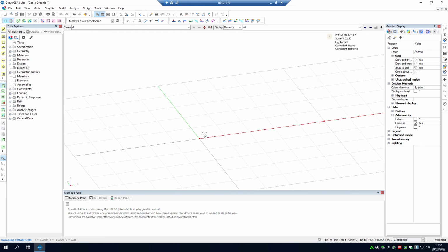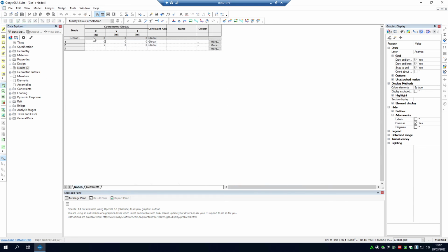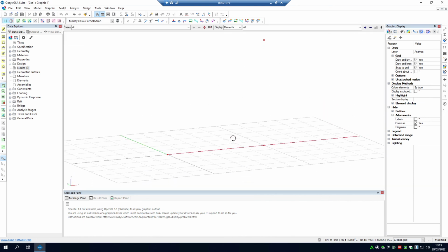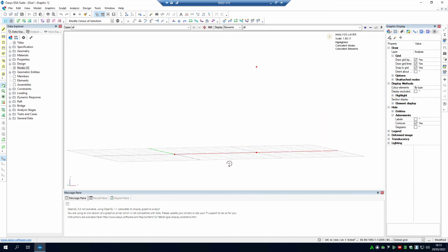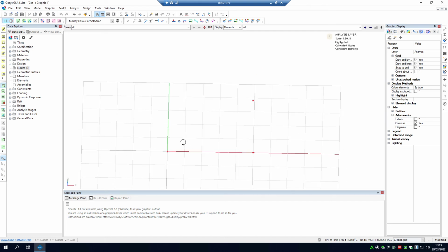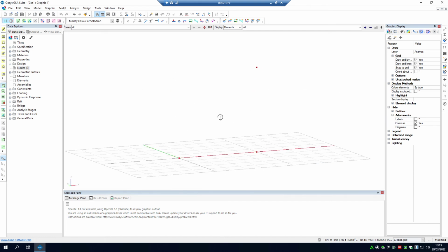You figure out where the node is in space, and then from wherever you start, you just apply the coordinates in real space. So for now, we'll go 5, 0, 5, 0, 0, 5. I'm using Z to go up because, as we mentioned previously, Z is up, and so therefore we have produced in the sky. If I set it to Y, it would be off in this direction, which we don't want.